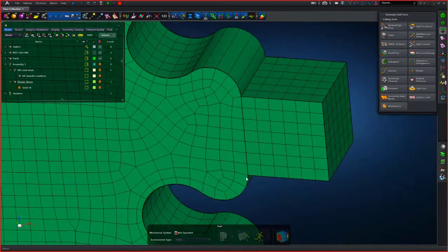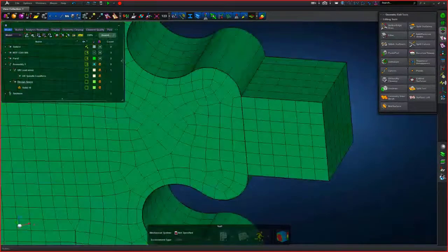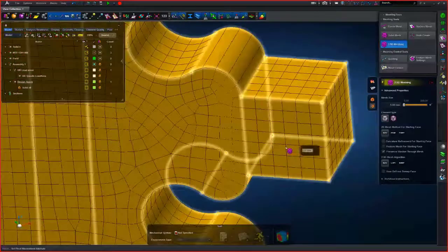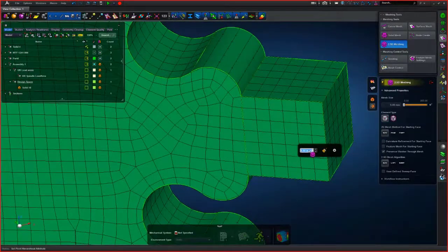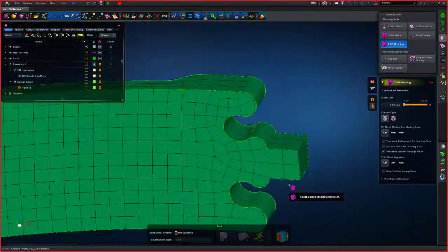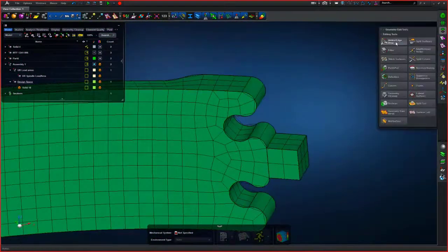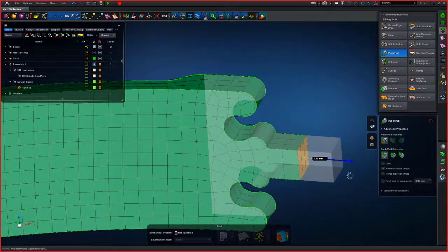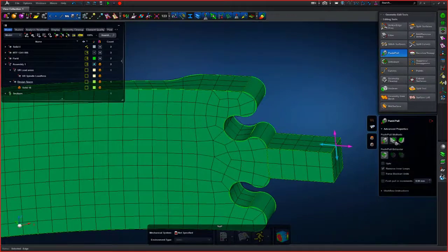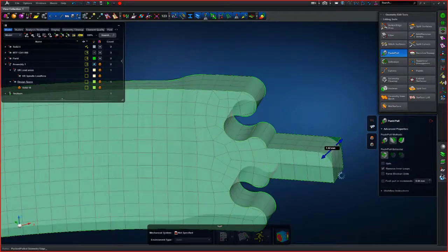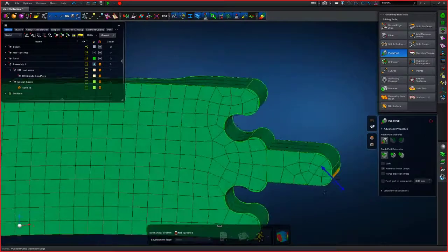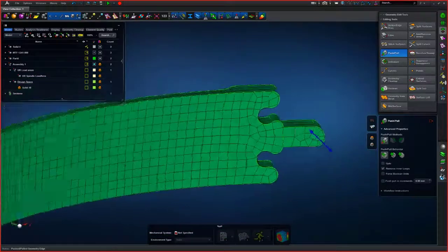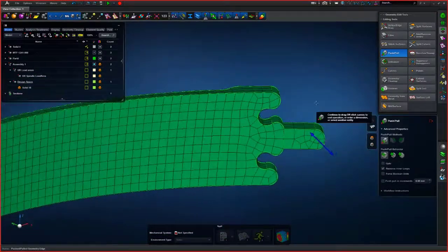What we could do is to just quickly go in and go to the properties and change this to, let's say, a much larger mesh, which updates quicker to illustrate the point. So again, the ability to do any CAD operation with only a few tools that you need to know, and you don't have to be a CAD wizard to be able to do that.